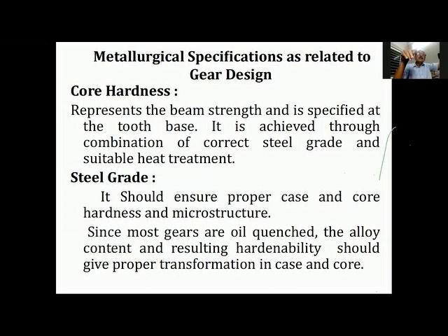So here, this is achieved through a combination of correct steel grade and suitable heat treatment. The suitable heat treatment is mainly the quenching. You have to select a proper quenchant to achieve proper core hardness as per the requirement, based on a certain grade.